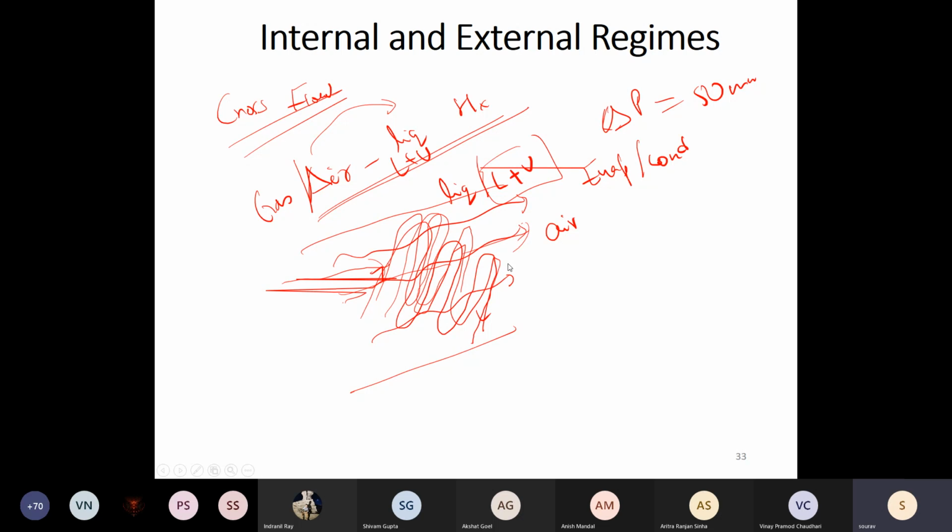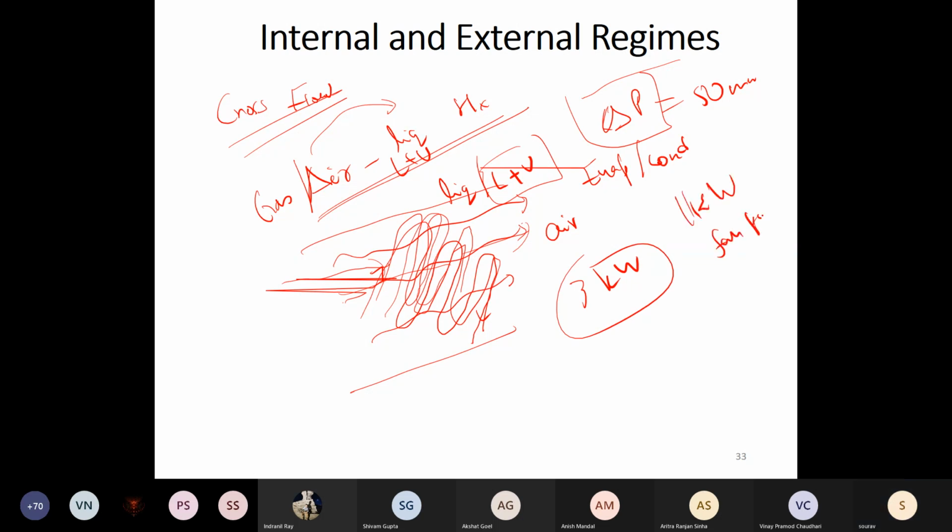Okay, so you will see that heat exchangers are not just designed from the point of view of heat transfer only, but the pressure drop also plays a very important role. So from heat transfer point of view, you may get small diameters, long lengths as the requirement. But in order to pump the fluid, if you require, let's say, 1 kilowatt of power consumption to blow air across the coil, then you will not prefer that when your heat transfer is probably 3 kilowatt. Let's say for heat exchange of 3 kilowatt, you require 1 kilowatt of fan power. Then this is a very poor heat exchanger design.